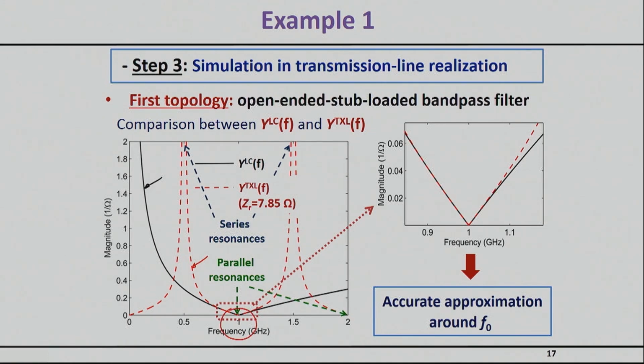And in fact, this is a nice view that is zoomed in very close to resonance. So I would say if you look at the resonance plus or minus 10%, you have nothing to be afraid of. Things are pretty close. But if you look at what happens at 0.5 gigahertz or 1.5 gigahertz, you have big trouble. And so you can expect that away from resonance, your response will be nothing like what you expect.